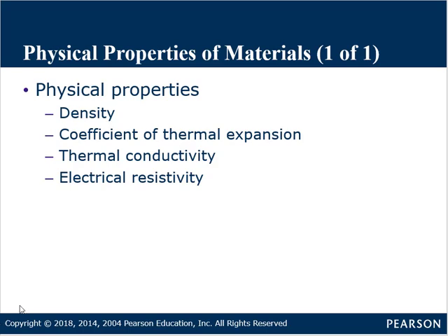One last slide I want to talk about here, and that is physical properties of the materials. We're mechanical designers, and we like to talk about mechanical properties, the strength of materials, modulus of elasticity, etc., etc. But there are other physical properties of materials that are important too. Namely, first one is density. It's a direct function of how much that material will weigh. The next one would be coefficient of thermal expansion.